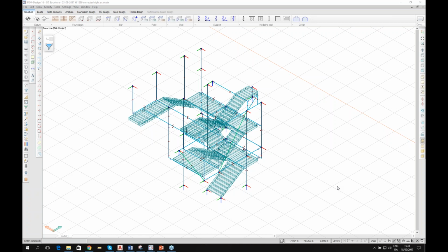If you snap to a different one of them, you cannot control which one you select, and you will have small displacements. FEM-Design is very fragile to these small displacements. So just make an effort to make the model correct.